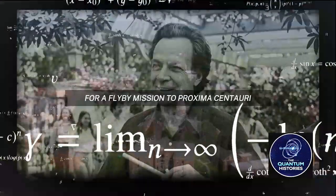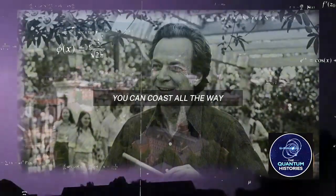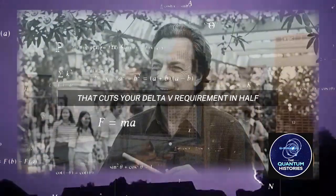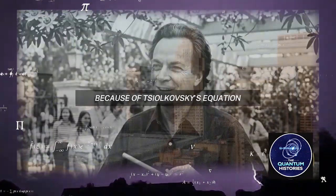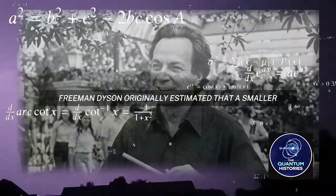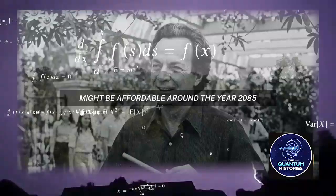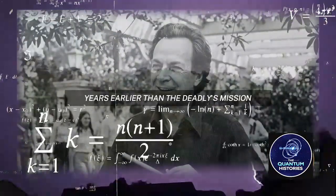For a flyby mission to Proxima Centauri, you don't need to decelerate. You can coast all the way and just zoom past at high speed. That cuts your delta V requirement in half. That makes it exponentially easier because of Tsiolkovsky's equation, that logarithm again. Freeman Dyson originally estimated that a smaller, simpler mission, a Dyson-class probe, might be affordable around the year 2085. That's more than 50 years earlier than the Daedalus mission.